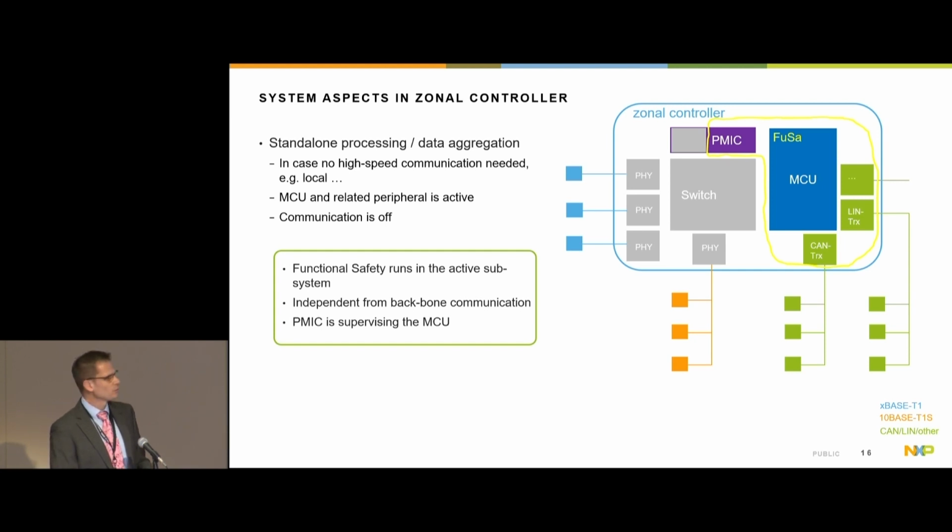In principle, it also works the other way around, so that you switch off the switch side, the communication side, but you just keep the MCU active, so that you maybe just capture data, or you're just looking for data which is coming in on CAN traffic, and then, based on the requirement or the actual situation, you wake up the communication when it is needed.